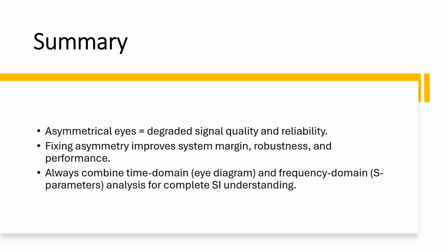So it's always advisable to combine your time domain analysis and your frequency domain analysis. When I say time domain analysis, we need to focus on the eye diagram, and then comes the frequency domain analysis. We usually focus on the S parameter extraction, where we talk about insertion loss, return loss, crosstalk, and the time domain reflectometry, that is TDR. Both of these analyses play an important role in order to create an end-to-end perfectly working or acceptably working channel at the end.